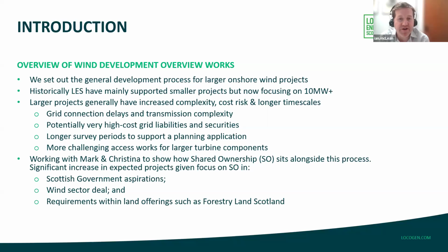And there are a number of differences between the smaller single wind turbine projects and larger wind farm ventures. And sort of really the grid connection. It's generally a lot more expensive and more complicated, as there's a need to factor in potential reinforcement to transmission networks or connection at transmission level, which can be magnitudes more in terms of the connection cost and also some of the costs in the run up to the project being connected.